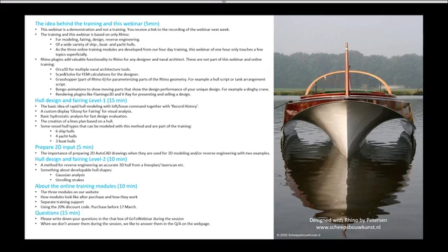This training is based on Rhino only. That was a very specific choice that I made right then. However, for naval architects, the Orca 3D plugin is an extremely valuable add-on for hydrostatic analysis, impact stability analysis, weight calculation, and today also CFD calculation is possible with Orca.